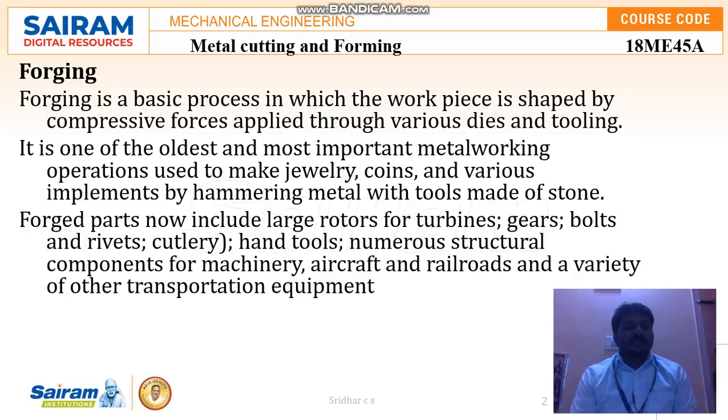It is one of the oldest methods we see in industries to get material deformation. When we apply load directly on any material, the material will be very hard. Hence we heat the materials. When the material is heated to a red hot condition, the grain structures will not be compressed. So when we apply force under those conditions, depending on the shape or size required, we can easily get it when we heat the material.